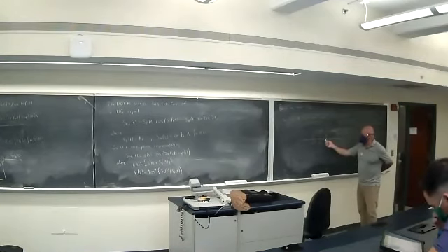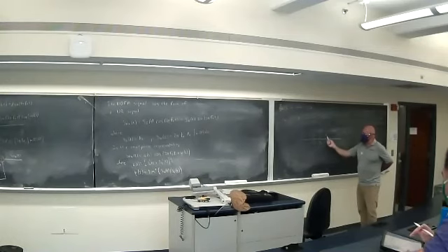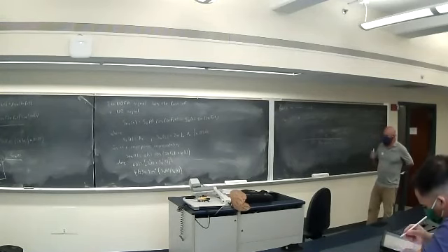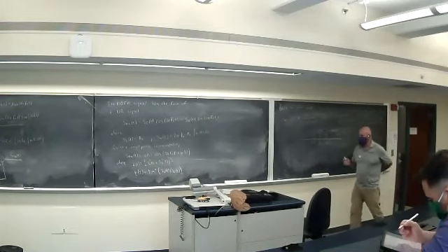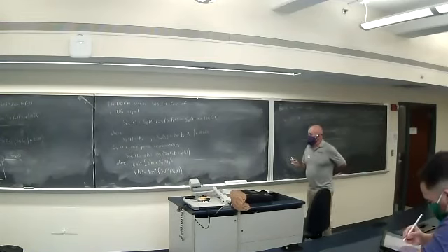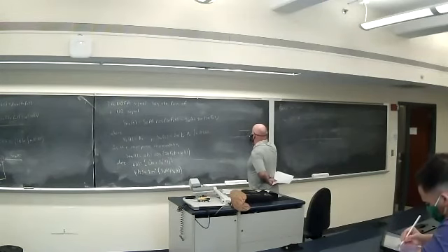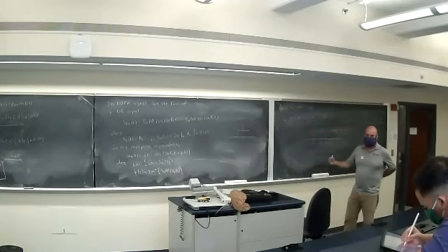We would actually have the integral of our message, the spectrum of the integral translated up around FC. How is the bandwidth of the integral of a message related to the bandwidth of a message? Well, in the frequency domain or the Laplace domain, to integrate, you just multiply by 1/S or 1/j omega. To differentiate, you multiply by S or j omega.